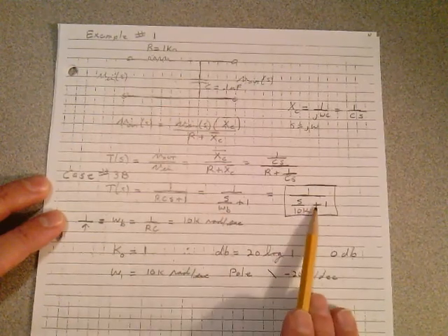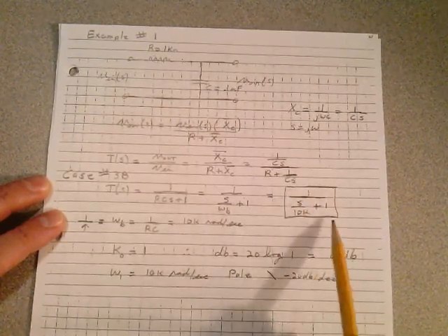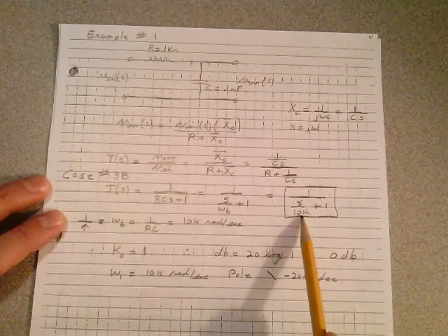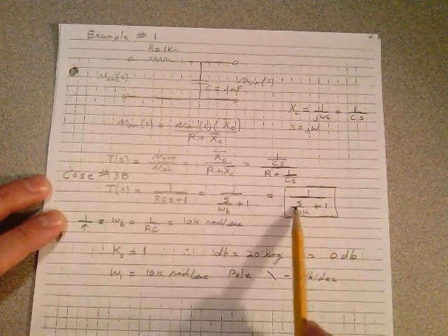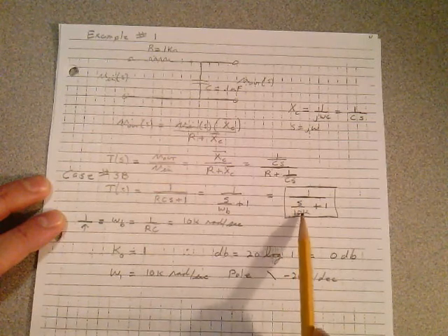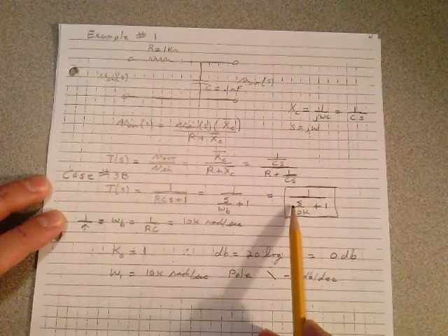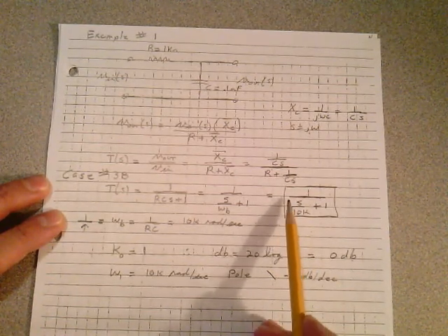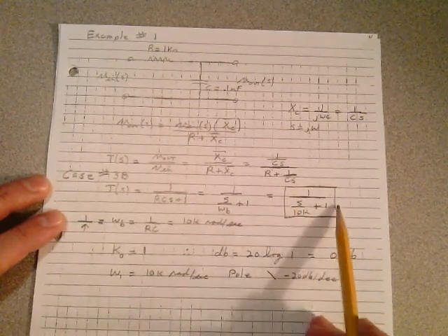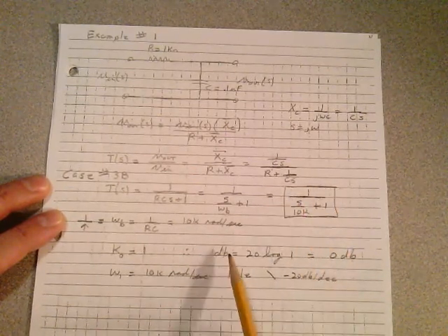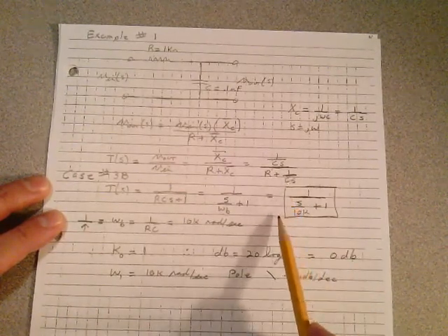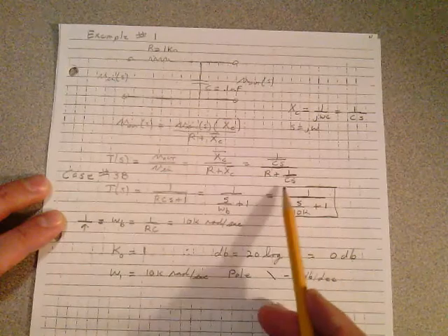I like to look at the time constant form in this format because it allows me to pull out the break frequency. But keep in mind, this is really the break frequency, but if you invert that break frequency and put it up as a coefficient on S, it's just the time constant. You have to get used to looking at it either way. But this is probably the easiest way to look at these transfer functions. So I can pull out the break frequency right here. That's in the format that we want, the time constant format we want.